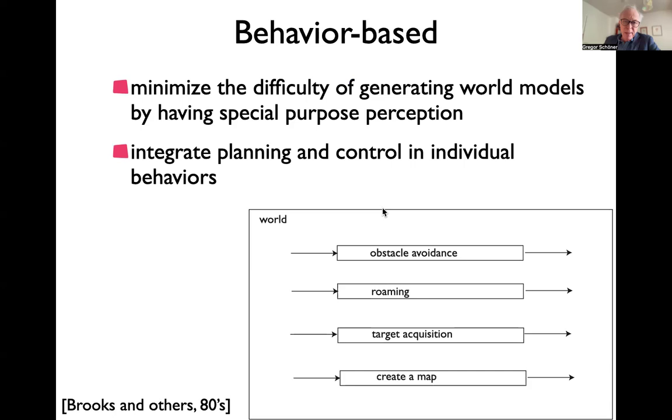Contrasted that with the behavior-based architectures in which the individual sense, plan, act things have trivial planning. That is, they sense, it's plotted horizontally here, their own sensors, and they have a very simple rule for how to act on sensor information that is directly translated into action. And then you might have multiple different ones. You call each one a behavior.